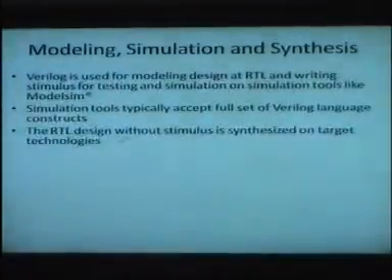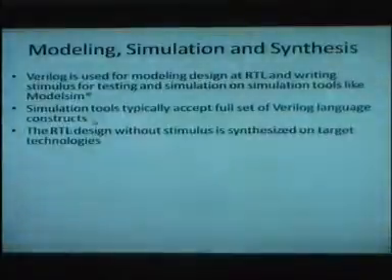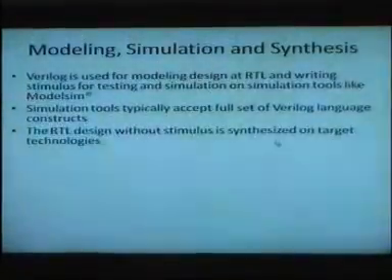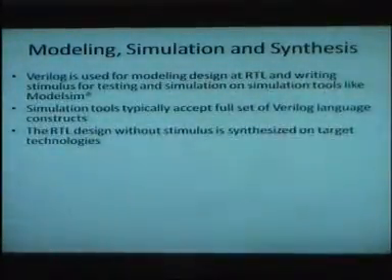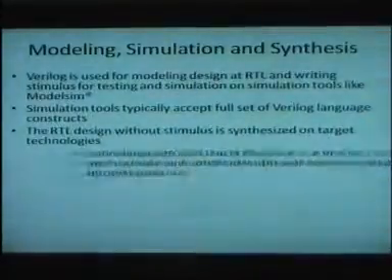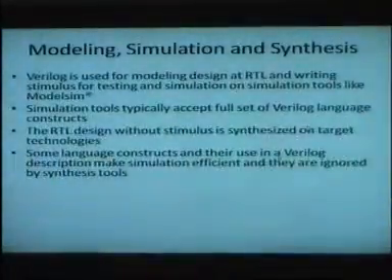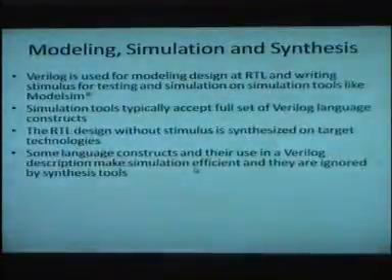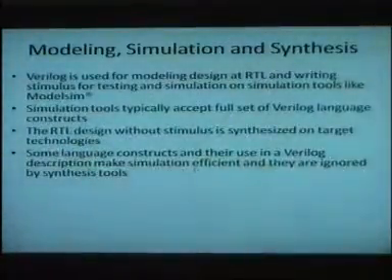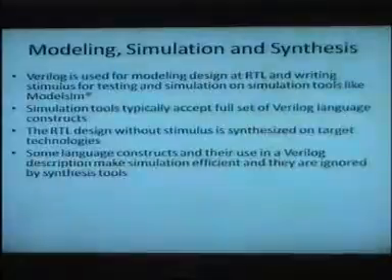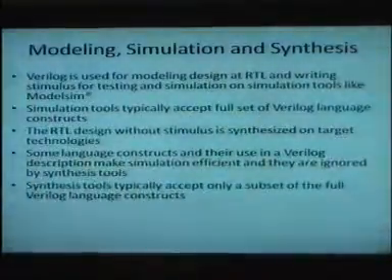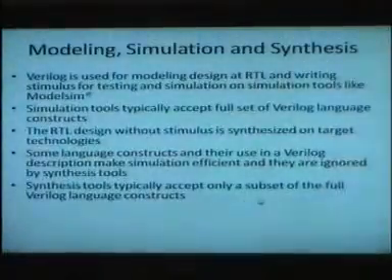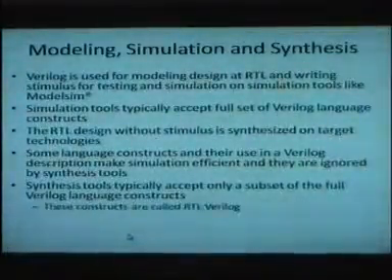So the RTL design. So this is the simulation tool. The RTL design without stimulus is synthesized on the target technology. Obviously, once you are synthesizing, you don't synthesize your stimulus. You only synthesize your DUT, which is the device under test. And there are language constructs in Verilog that are ignored by the synthesis tool. It'll ignore them and will not complain. For example, timing statements you put, it'll ignore. And for the others, it'll complain. Synthesis tools typically accept only a subset of the full Verilog language constructs, and that is called RTL Verilog.